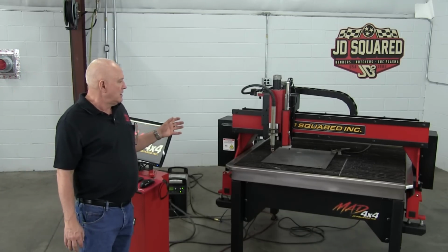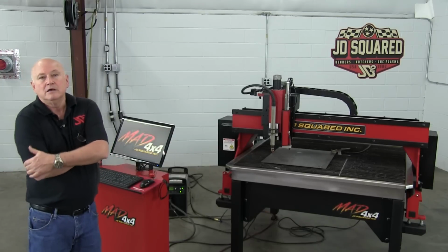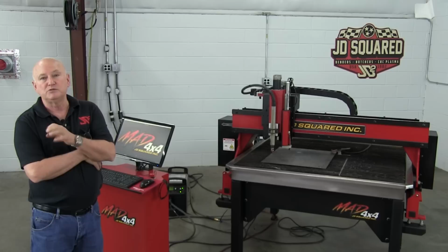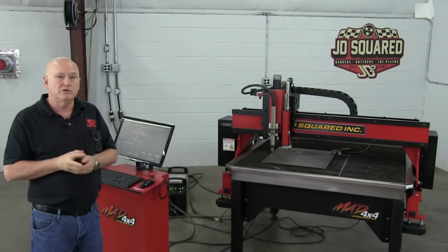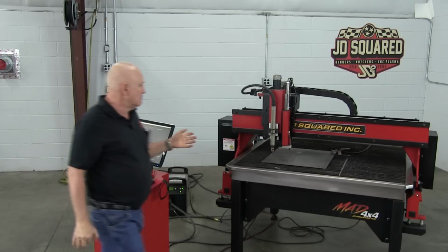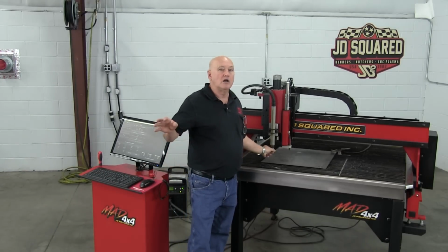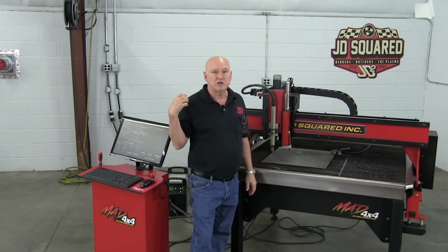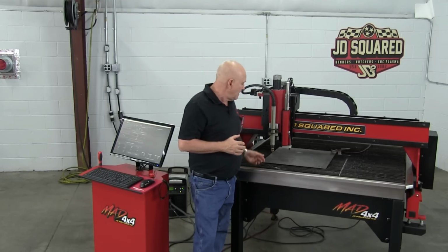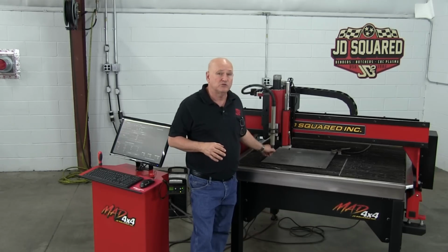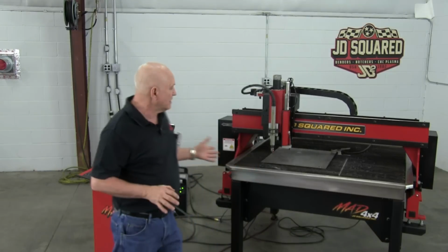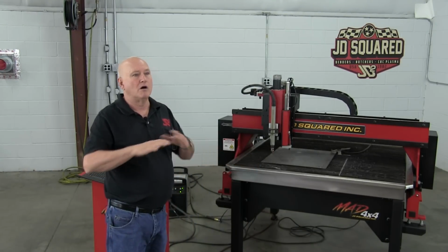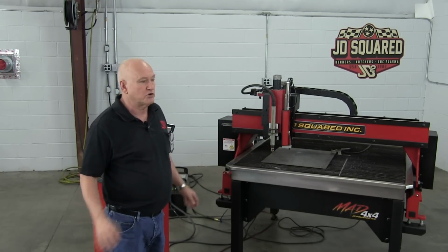What we've done in version 2, we've added features called consumable groups and consumable tracking. And what this means is, whenever you cut a piece of metal out, the consumables are literally the end-all of end-alls. If you tell your machine that you've got 85 amp consumables and it's set to run at that, but you've actually got 45 amp consumables in there or vice versa, it's a bad day for your metal. Nothing's going to cut right. The kerf width will be wrong. There'll be more slag. It's just a train wreck.